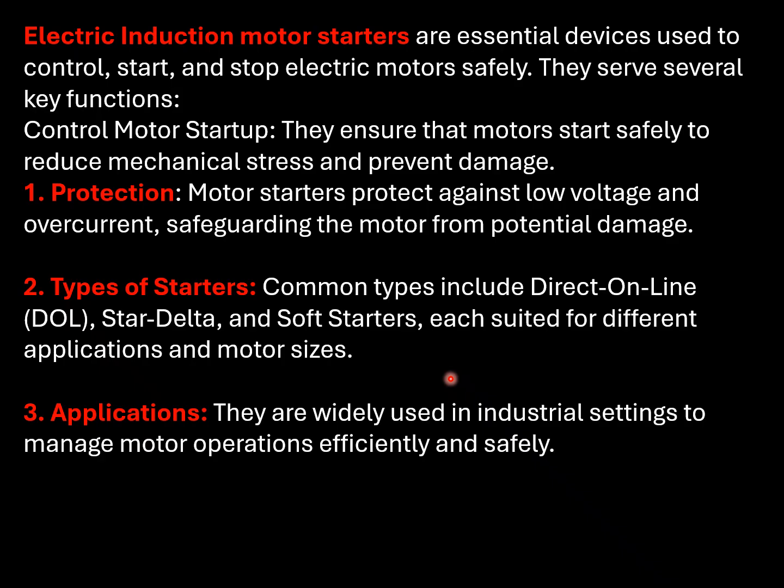Motor starters protect against low voltage and overcurrent, safeguarding the motor from potential damage. Third, the types of starters. Common types include direct online, DOL, star delta, auto transformer type, and soft starter, suited for different applications and motor sizes. They are widely used in industrial settings to manage motor operation efficiently and safely.